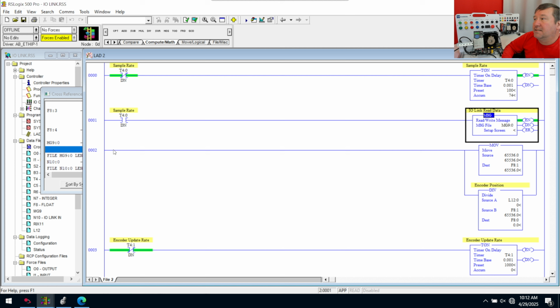In our previous two videos, we talked about how you can take an RSLogix 1100 PLC or an RSLogix 1400 PLC and use it to both control a PowerFlex 525 drive, and we can also pull data over IO-Link, which includes this encoder position. Which got me thinking, now we have this controlling our motor, and we have feedback. Well, we're only one step away from learning about PIDs.